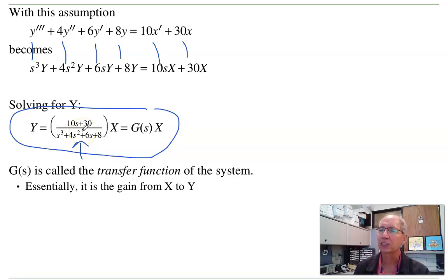What that means is this is a filter. If I take a sine wave applied as an input, s changes for each frequency. As frequency changes, the gain changes. It's a filter.